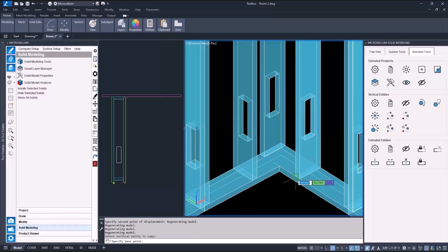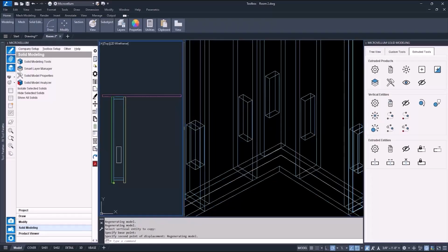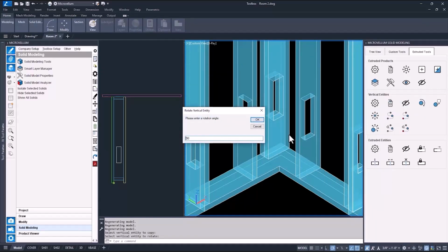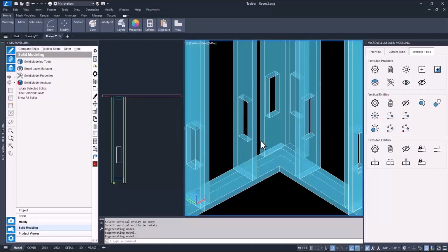Now copy this next one and do the same thing. This time I will need to rotate it, and here's the button for that. This is its current angle, so just need to change that back to 0. And the last step is to move it back where it'll land on the frame. This time select the move option where it can move anywhere in space. Pick the part. Now I'm just going to pick a starting point of that part, move the cursor over in the direction I want it to move, and give it an amount. This will be 3/4 the thickness of the part.